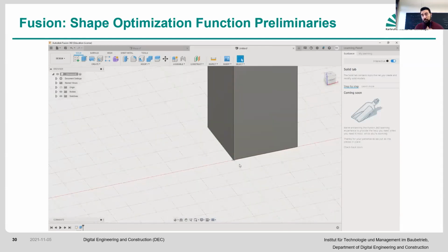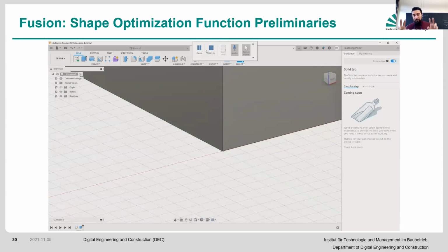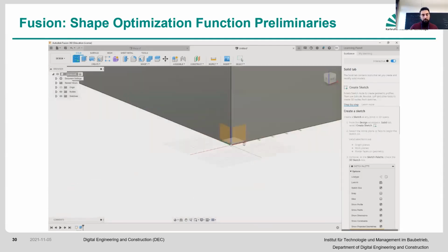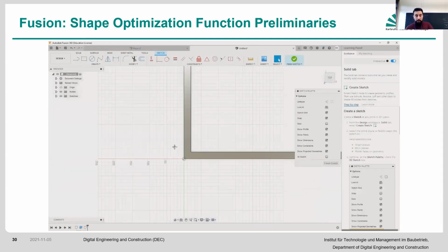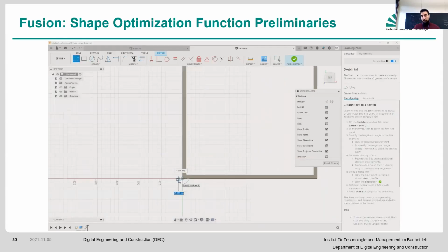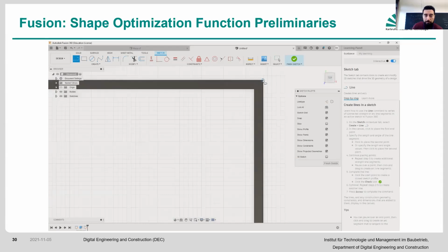Once you have that, the next step is to have the base, basically the footing of the column, or this tube that we've created here, or this hollow structural section. Again, we have to find the exact same plane that we've modeled this for. So we do the orthogonal plane at the very bottom. We again introduce our larger rectangle, and this is going to be a 2 centimeter by 2 centimeter extra. This is just for the requirements for your constraints and the supports there, nothing more.